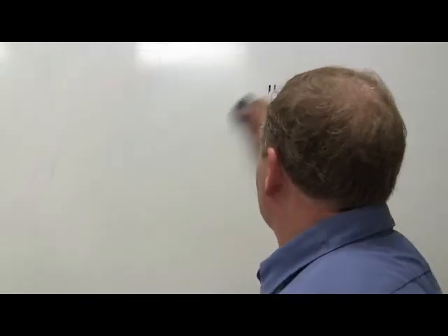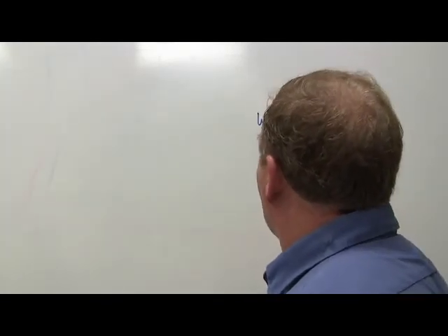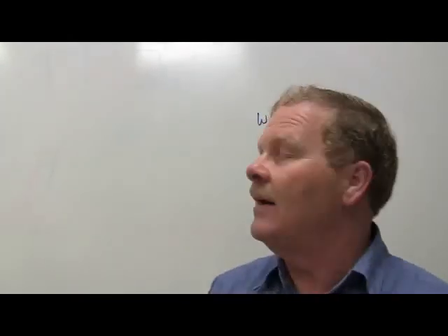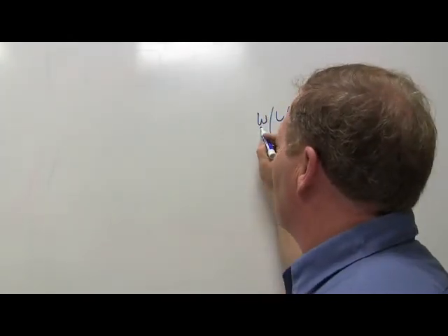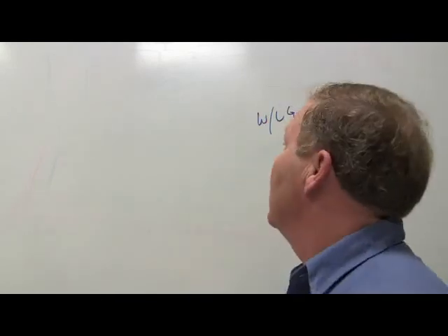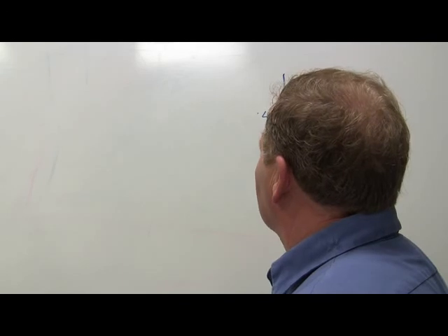Basically, what we're talking about here is you're going to see something that says white, light green, something like that. This right here is the primary color of the wire. This right here is the stripe. The stripe's on the right side of that slash, right? On a Mercedes, what if the wire had an SW next to it?